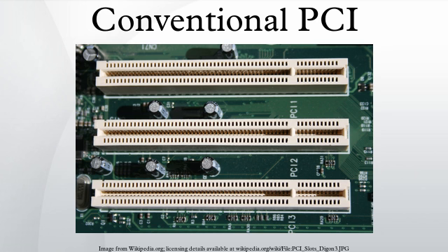Unlike I/O space, standard PCI configuration registers are defined so that reads never disturb the state of the device. It is possible for a device to have configuration space registers beyond the standard 64 bytes which have read side effects, but this is rare. Configuration space accesses often have a few cycles of delay in order to allow the IDSEL lines to stabilize, which makes them slower than other forms of access. Also, a configuration space access requires a multi-step operation rather than a single machine instruction. Thus, it is best to avoid them during routine operation of a PCI device.